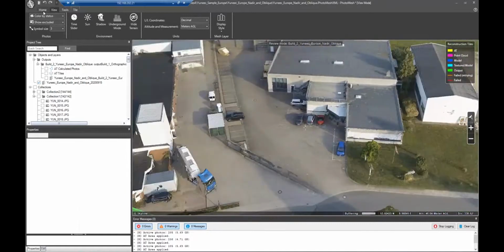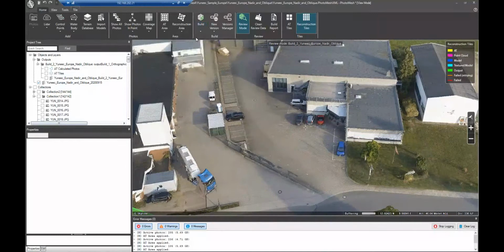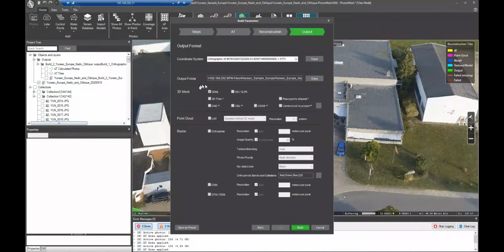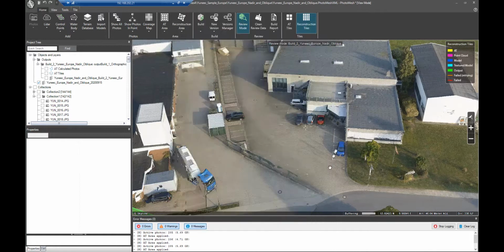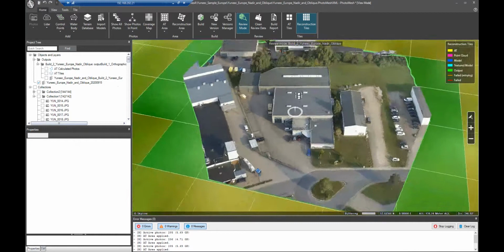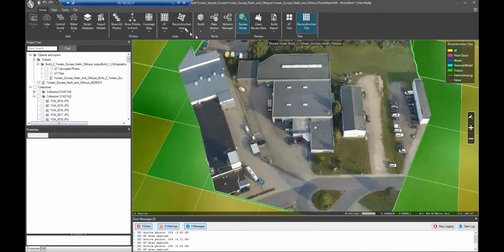Once the 3D is done, first of all, it could be exported into 3DML and brought into TerraExplorer. There's also the option to export other formats in the PhotoMesh Pro version, as well as export the dense point cloud, either from the photo correlation or the 3D model, which is what we're seeing here in point cloud format. The true-ortho, the DSM and the DTM. So a lot of additional outputs from the derivative products that the 3D mesh produces.